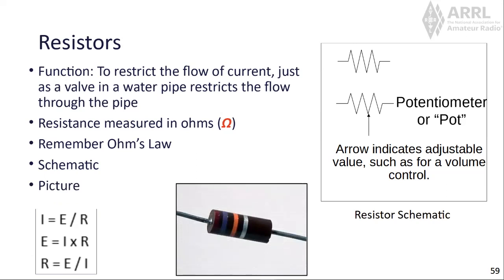Resistors. Okay. We see a picture of a resistor. Resistors have a color code, which helps us identify the resistance value of that resistor. It will tell you what the actual resistance is supposed to be, and then the last band, in this case the silver band, would also tell you the tolerance on that resistance. In other words, 5% accuracy, 10% accuracy, etc.